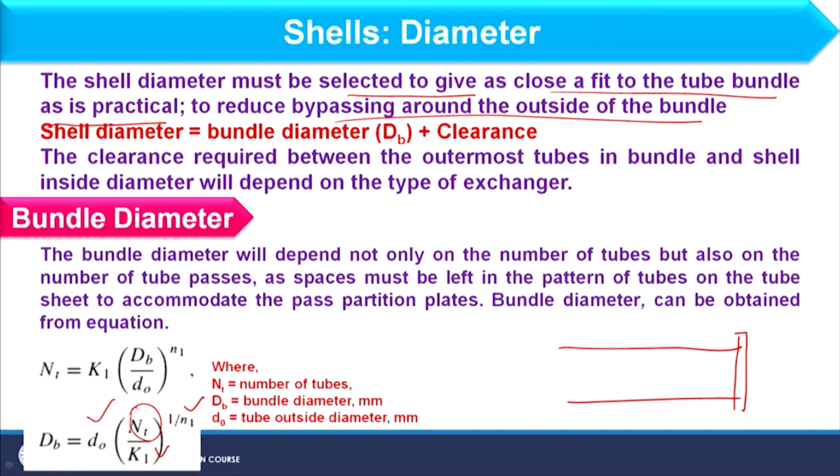Okay. So to illustrate that, we will first focus on the exchanger. Okay, this is the simple exchanger, this is the tube sheet, right. And here we have the inlet and outlet nozzle. Now what will happen? Pass partition plate is usually available in tube side, and which is this. Okay. However, I am considering this plate, and based on that I am deciding the bundle dia. Fine.